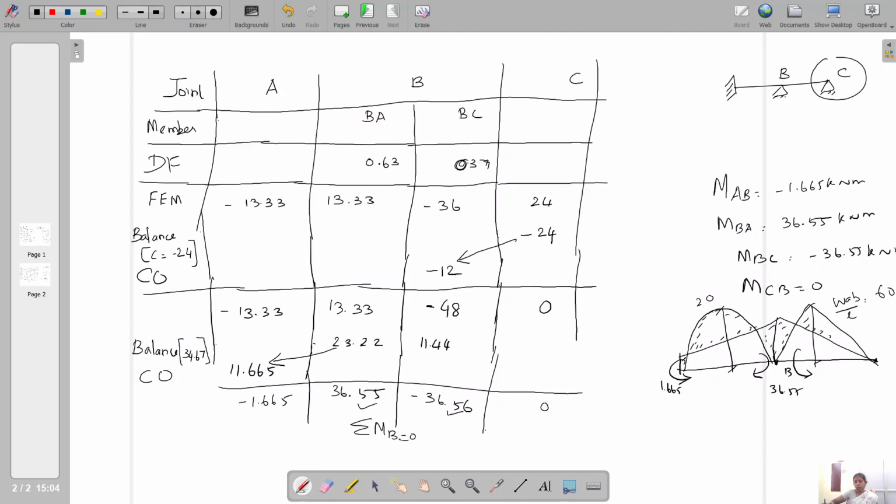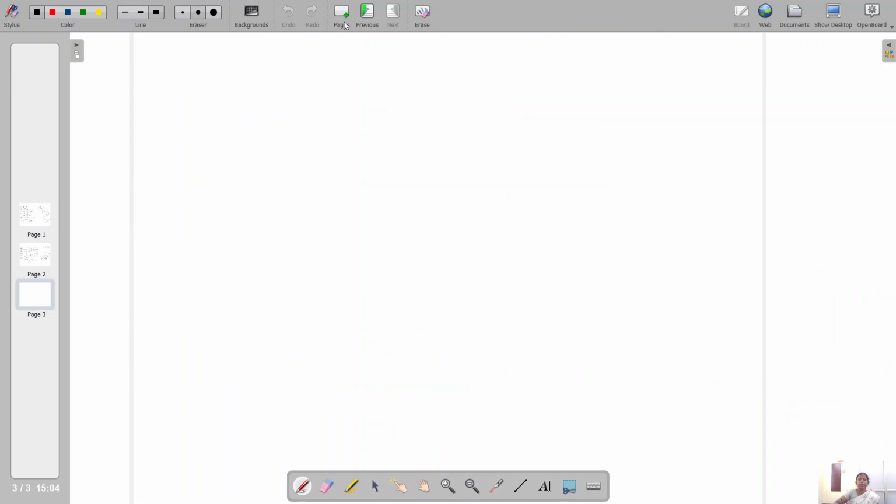And you note how to calculate the reactions from the bending moment value and how to draw the SFD. So we have to complete the problem up to the reactions. So mark the moment 1.665 here, 36.56. We have the loading of 10 kilonewton per meter, and the support is RA. Here I am naming it RB1. So I am going to find RB1.